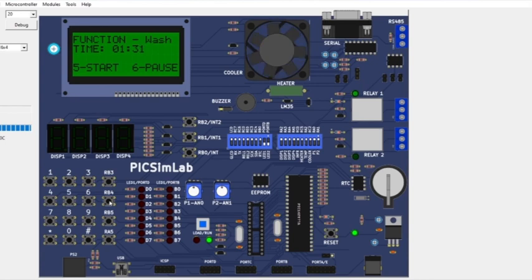If there is any interrupt in between, RB0 is the interrupt key. If you long press RB0, a buzzer sound is heard. This buzzer sound indicates the door is open and should be closed immediately. After releasing the RB0 button, the program will continue as usual. The time is 1 minute 16 seconds now. After it completes, another buzzer sound will be heard, which indicates the completion of the program.